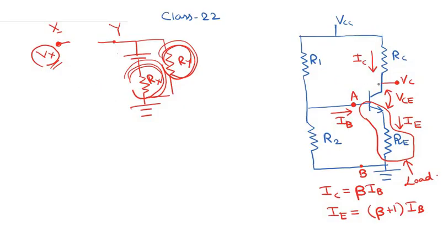In a similar way, when I increase this voltage Vc and there is no current change across the base, I can conclude that the base and the collector are electrically isolated as far as the behavior of the circuit is concerned, or there is infinite resistance between the base and the collector. So between the base and the collector, I can replace it by infinite resistance. Let me delete this base and collector here, and replace it by an infinite resistance.